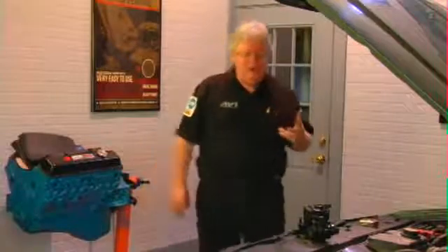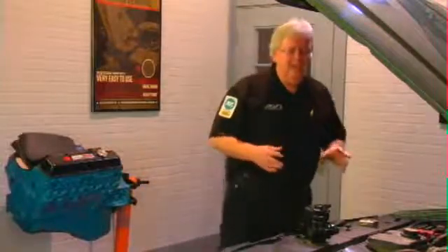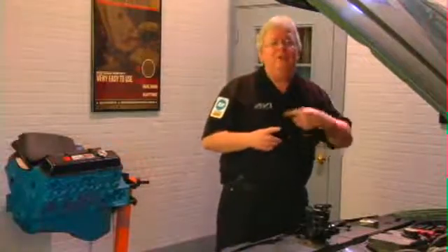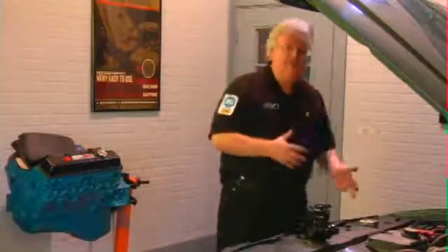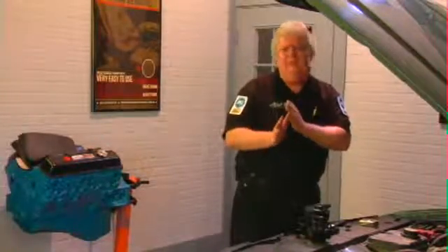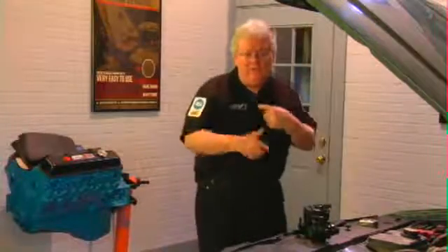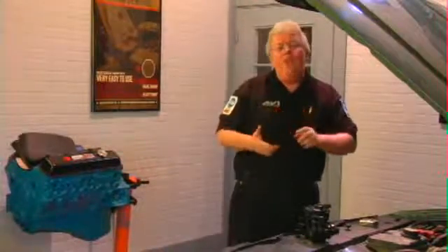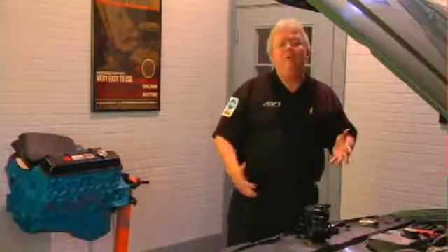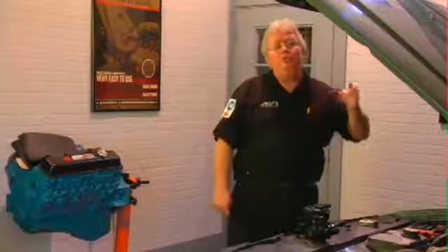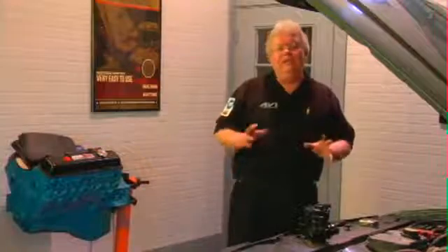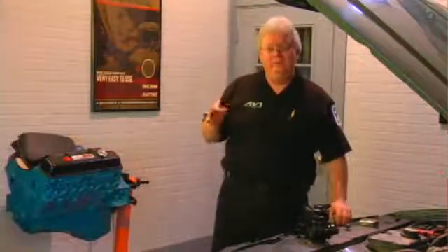Also, and you may have questions come up like this, you want to make sure the pulley itself is straight. As you rotate the pulley, maybe take the belt off or at least run the engine and eyeball all the pulleys on all belt-driven accessories, not just the power steering pump, because it's in line with all the rest of them. Make sure you have no wobble and no damaged face of the pulley or something like that. And of course, look at the belt quality. Are there too many cracks in it? Is it glazed? All the usual things that we look at on drive belts prior to making a decision whether we need to replace them or not.